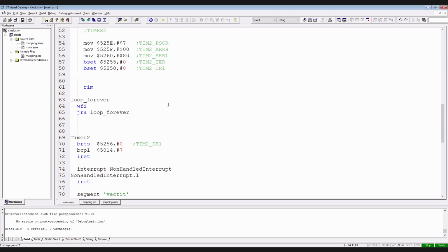It clears the interrupt mask of the condition code register, which enables the interrupt possibility. You can treat it as an enabling switch. If it's present, then the interrupts are also present.